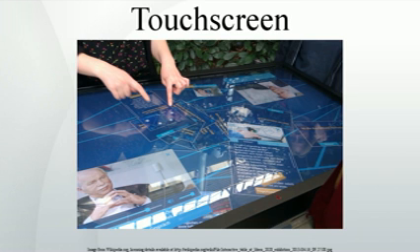Technologies. There are a variety of touchscreen technologies that have different methods of sensing touch. Resistive. A resistive touchscreen panel comprises several layers, the most important of which are two thin, transparent electrically resistive layers separated by a thin space. These layers face each other with a thin gap between. The top screen, the screen that is touched, has a coating on the underside surface of the screen. Just beneath it is a similar resistive layer on top of its substrate.